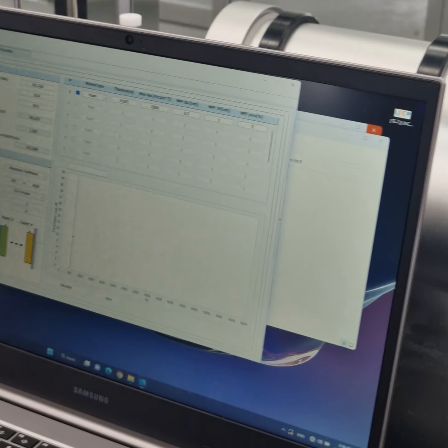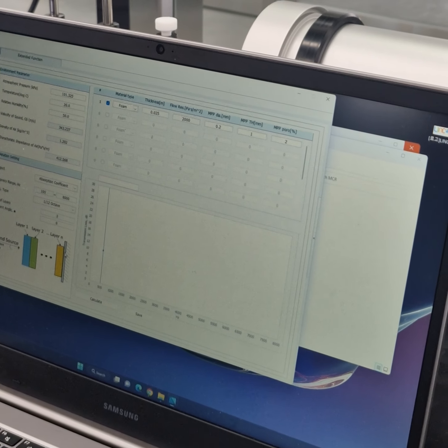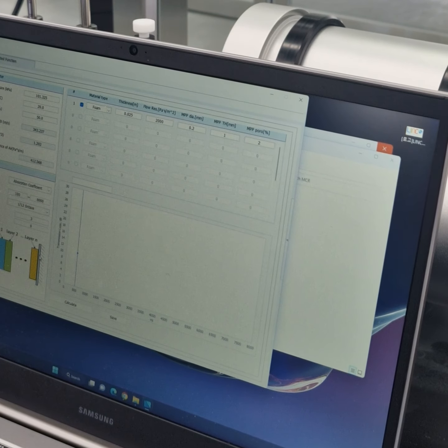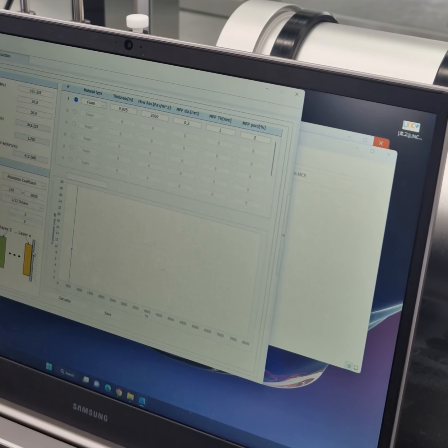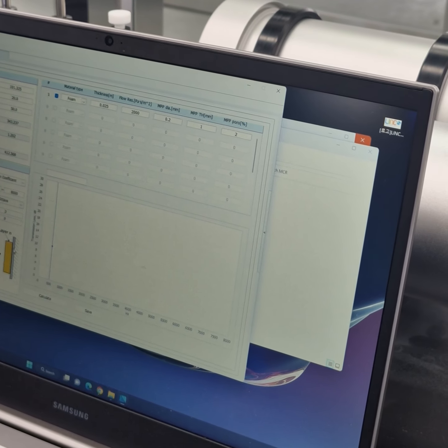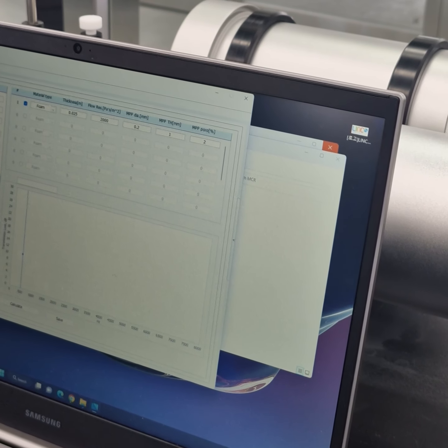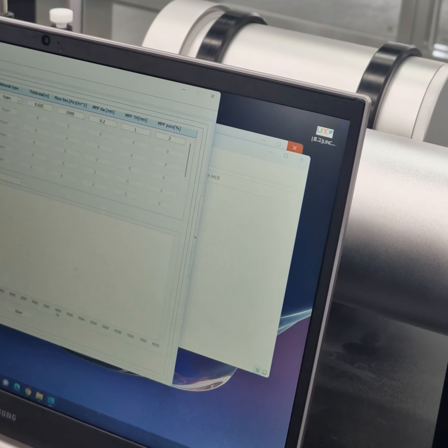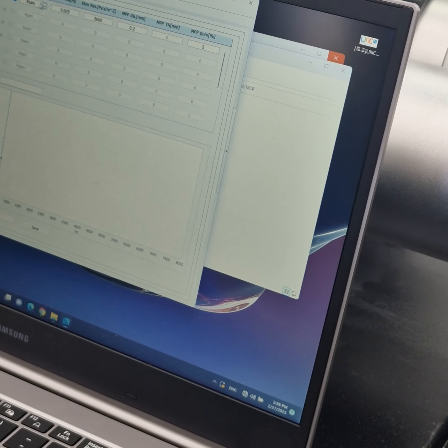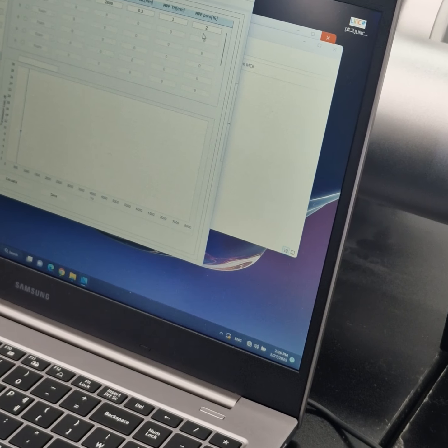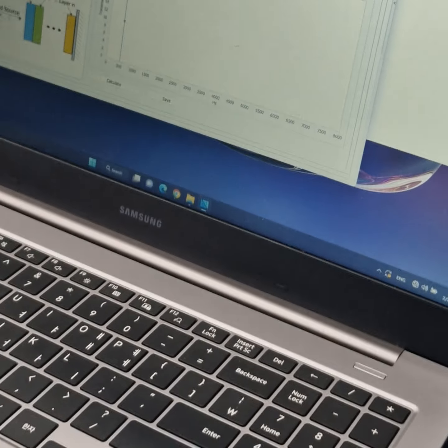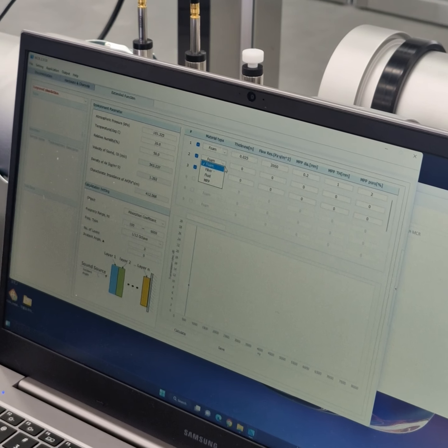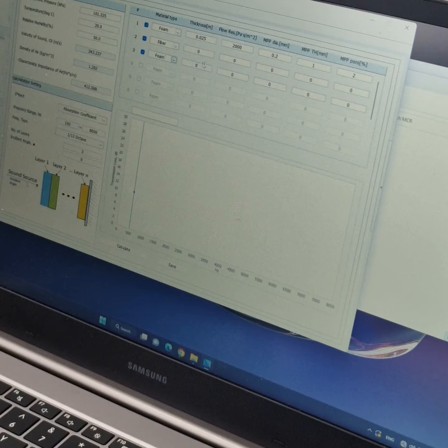So if you wanted to simulate different layers of material stacked together, like I have a foam, a fiber, and a foam, three layers of the sample with different flow resistivity, then we can use this type of function. To add it up, you can see I can select three layers: foam, fibers, foam.